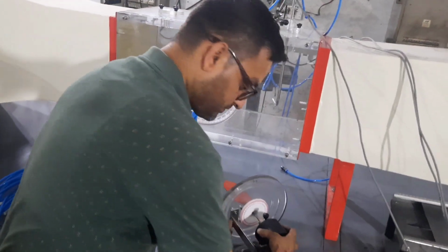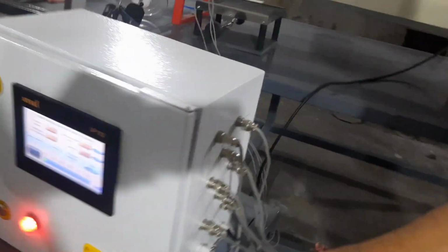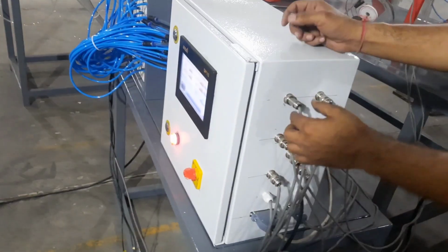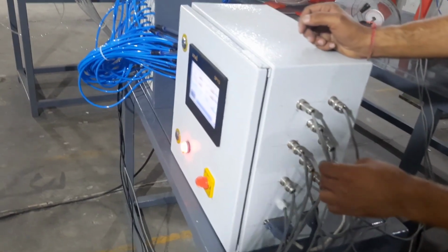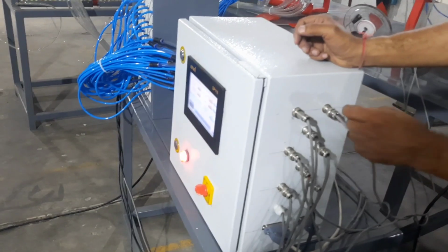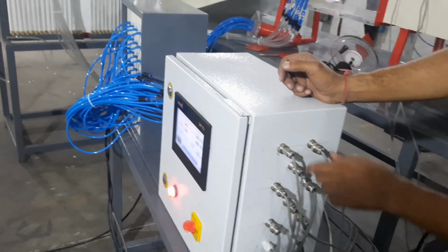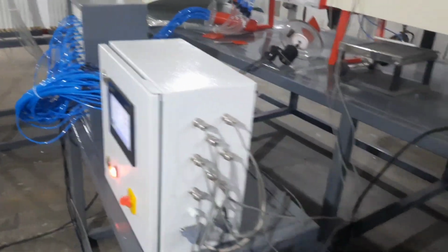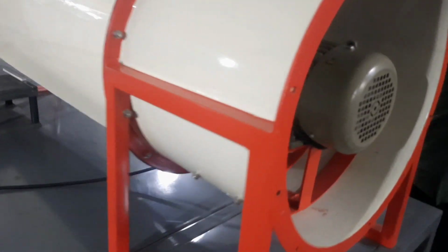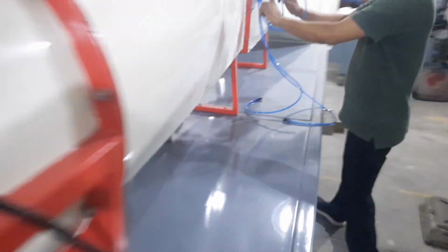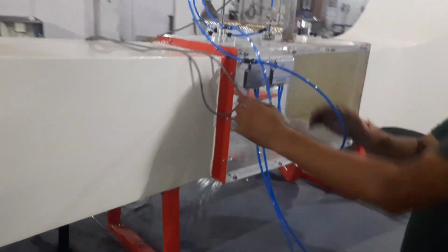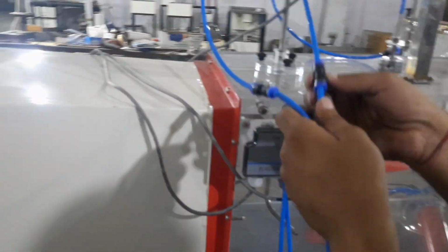So there are connectors given that are to be connected on the side of the control panel. The first one will show you the differential pressure, the connector for the differential pressure. The second will show you the velocity, which is calibrated directly in velocity. On the side of the test section, two differential pressure transmitters are installed with the connectors.